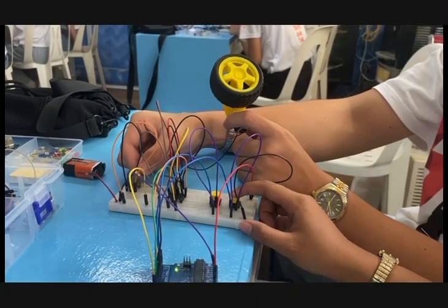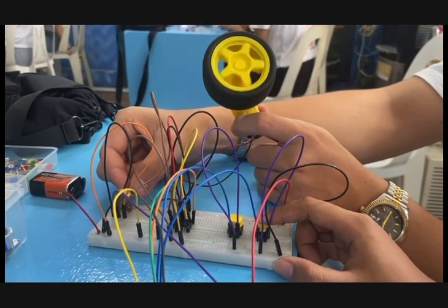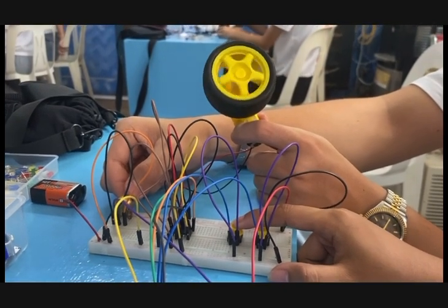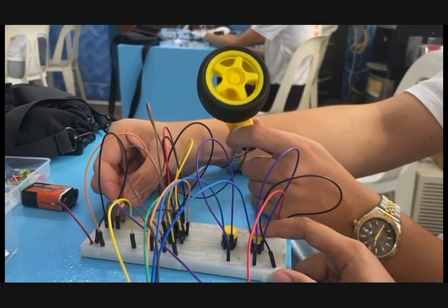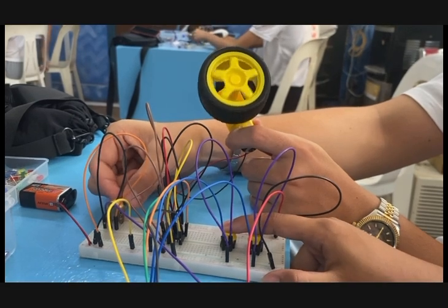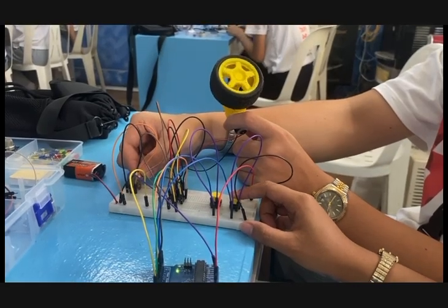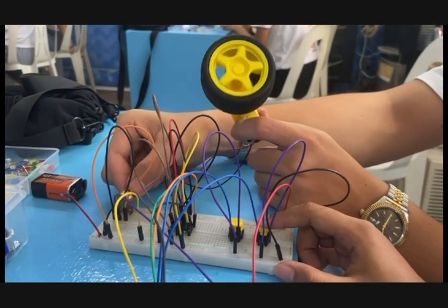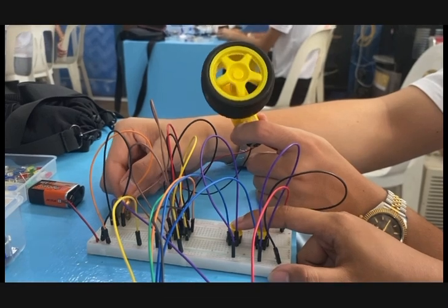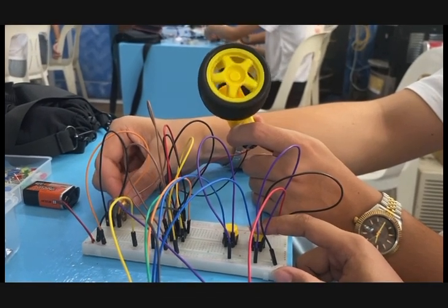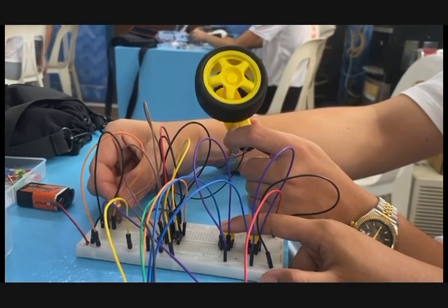We controlled both the direction and speed of a DC motor using two push buttons and the potentiometer connected to the L293D motor driver. The button set the direction, while the potentiometer adjusted the motor speed through PWM. We faced unstable changes, which we fixed by tightening connections and calibrating the potentiometer. This setup can be applied in remote-controlled vehicles, adjustable fans, and robotic systems.